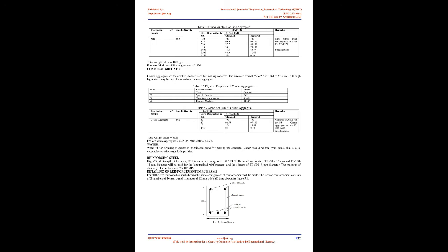The molten glass is then allowed to flow through fine holes in a platinum plate. The glass strands are cooled, gathered, and wound. The fibers are drawn to increase the directional strength. The fibers are then woven into various forms for use in composites, Fig. 1.3. Aramid fiber reinforced polymers, AFRP.